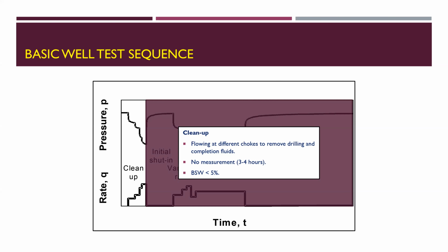But in this case, it means we have perforated in the water zone. And I guess when we perforate in the oil column, the water there is immobile water. So the only case that water is coming is either we have channeling behind the casing or we mistakenly perforated in a water zone. So in those steps, you'd recommend a production logging tool to identify the water ingress route? It depends on the availability. If the tool is available on location at this time, we can run it.